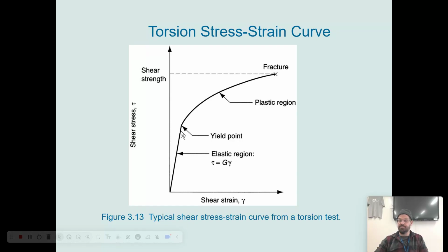But whenever you do these shear strength tests, you're going to hit a yield point where if you exert more force than that over that surface area, it's going to permanently change shape, right? And that's why the graph starts to turn curved, and it means that you have to apply less and less force per surface area to get it to strain more and more.